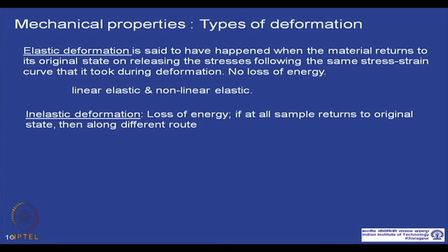Second is your inelastic deformation. In elastic behavior, if you give the stress, give the force, the energy is stored in the material. So, when you release the stress, that energy is given back. So, you get back to the original state. Whereas, in case of inelastic deformation, when you apply some force, the energy is lost.